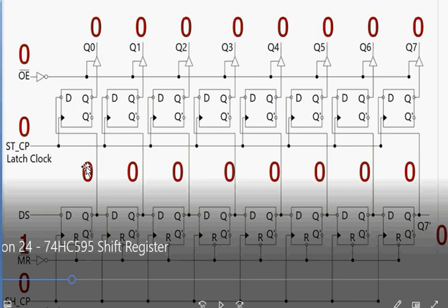Now the next bit is 1 and then another 1, so shift the data again using the program, and to receive that data, make this clock high. Once the data goes onto the shift register, you have to pull that clock pulse low; only then, during the next iteration when you make it high, can the data be transferred properly. This way it goes. Now assume that after application of 8 serial shift clock pulses, you have all the data.